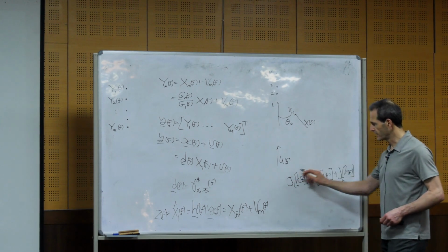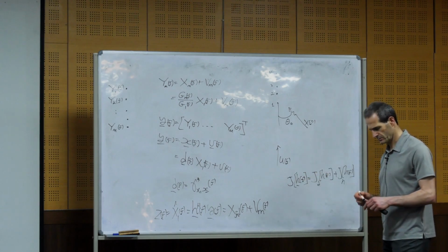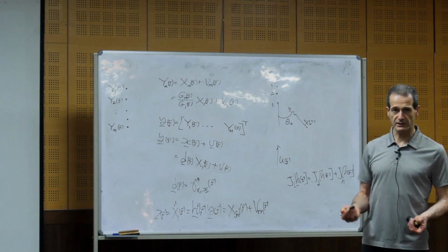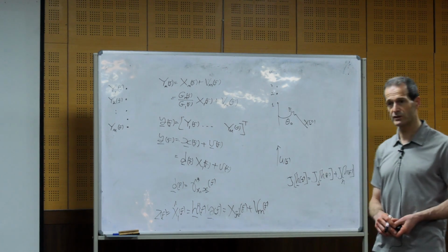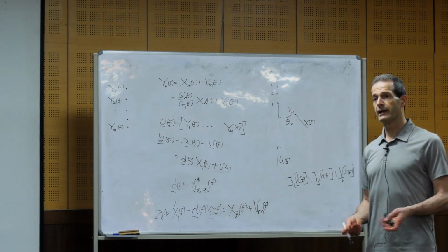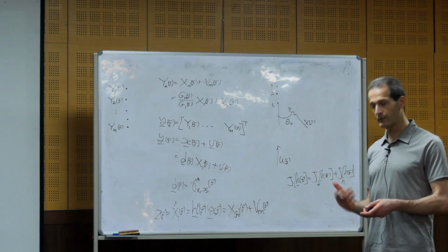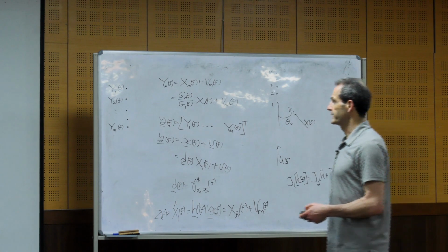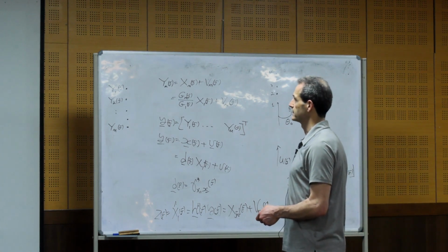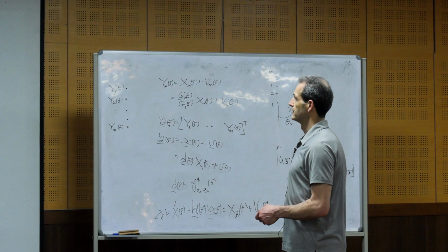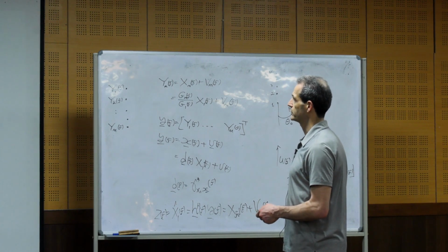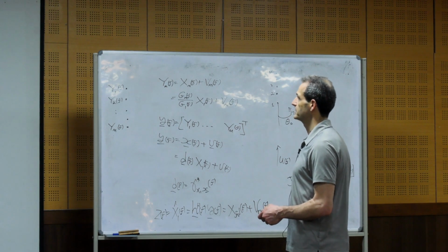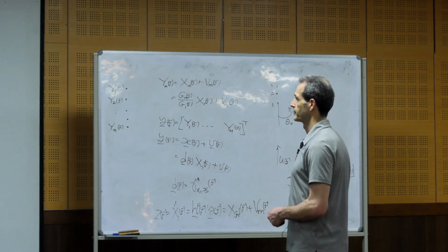So we obtained an expression for this. This is a scalar function of a vector. And we know how to find the derivative or the gradient of this function with respect to a vector and equate it to 0. And then from that, we find the optimal vector. If we find it, we see that it looks like this. This is the optimal vector, which minimizes the narrowband mean squared error.